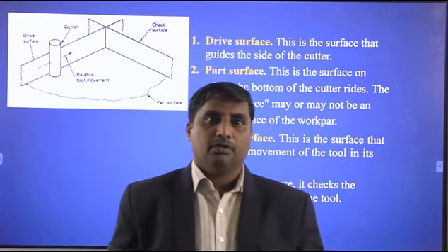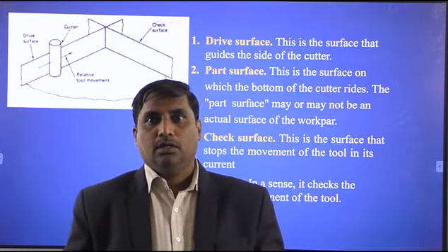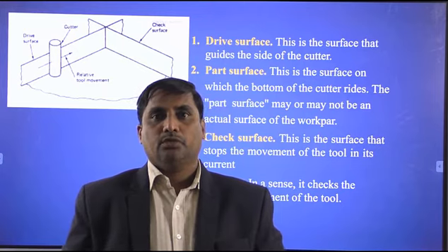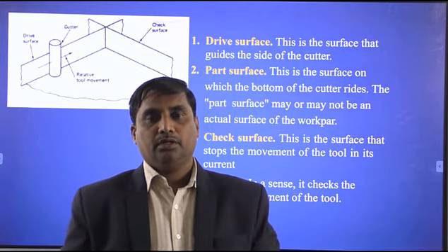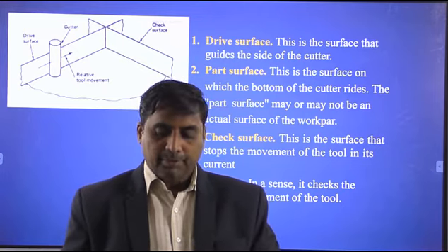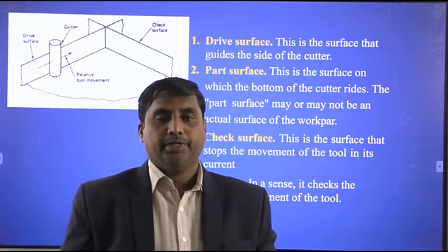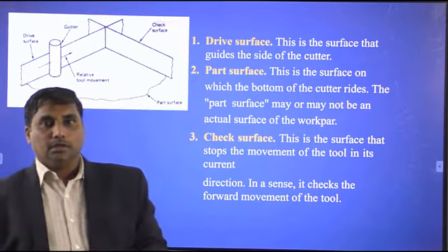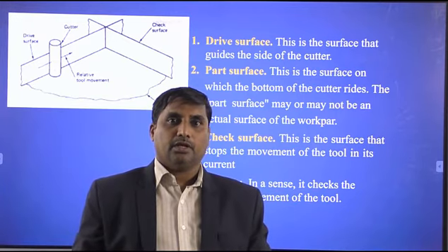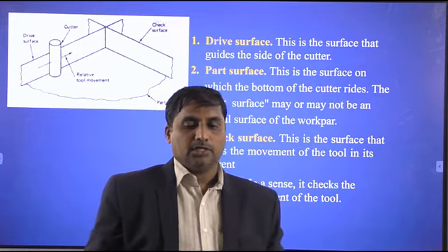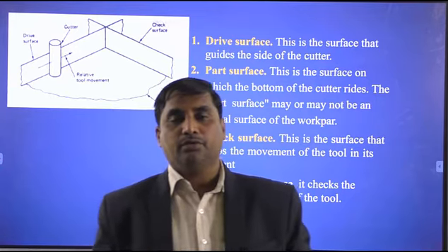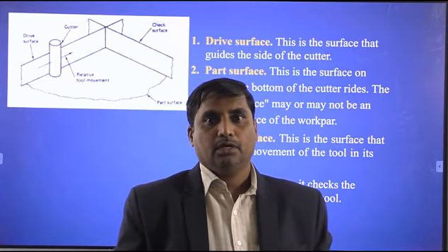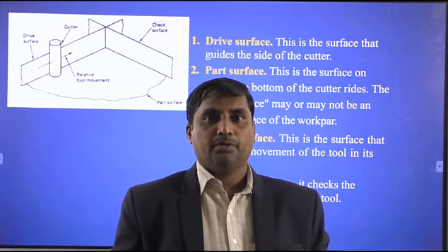In the previous lecture we learned about the rapid motion statements and geometric statements. Regarding motion statements, I explained the rapid traversal and incremental movement of the cutting tool by taking two examples. Next is generating contour shapes, that means irregular shapes. In that case, we have to continuously guide the cutting tool to get the required shape of the work part.